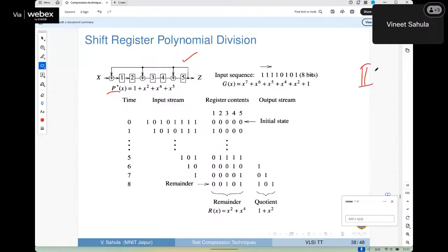Type 2. Now we take this LFSR and take the corresponding polynomial division. So my sequence can be converted, right? If I take this as MSB or whatever. So possibly I'm taking this as MSB. So I'm taking the type 1 LFSR, whatever. So if this is LSB, this is 7, 6, 5, 4, and 3 is not there, and 1 is not there. This is a polynomial.